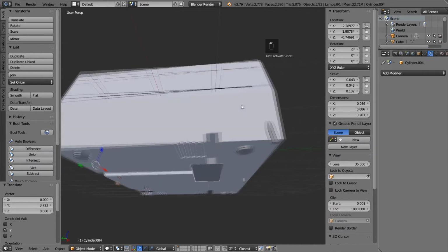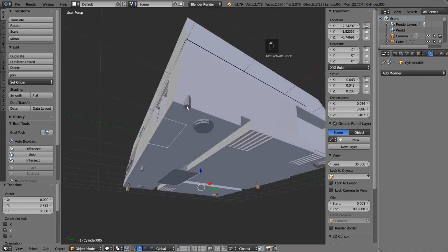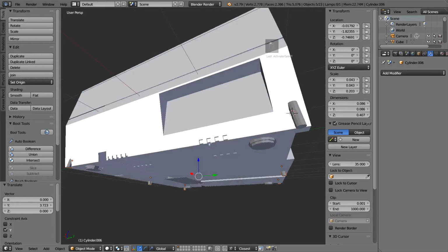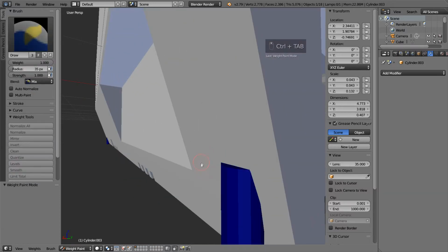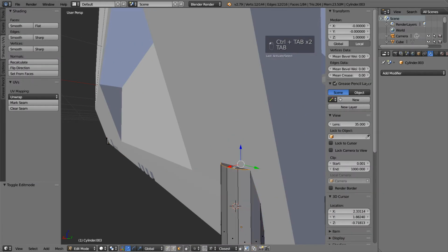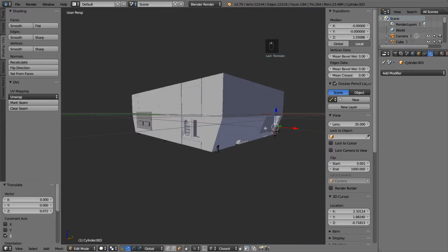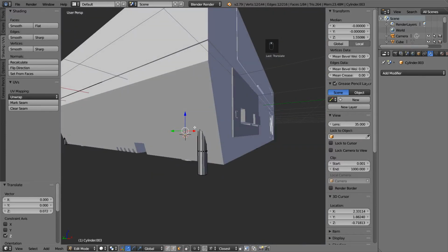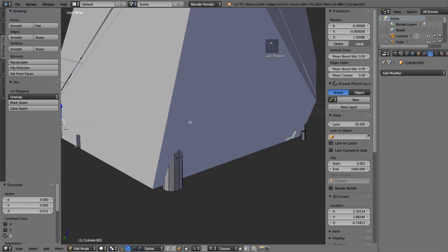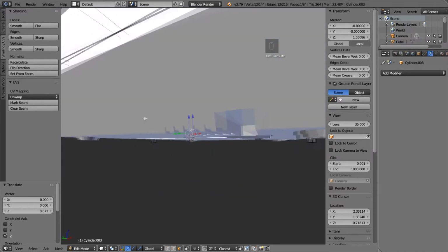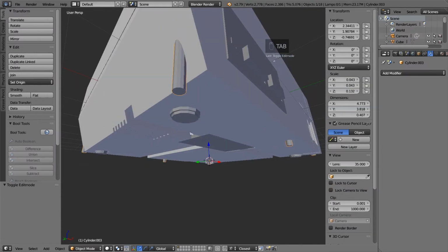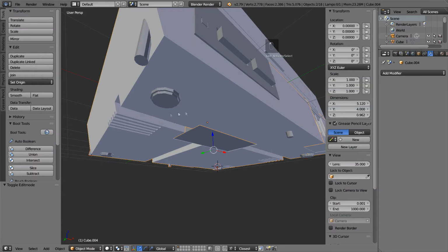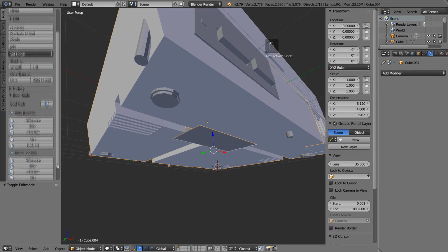Let's select all the cylinders. And then, once selected, we can hit Ctrl J. As you can see, this one is not fully intersecting. So let's bring it up a bit, make sure it's right in there. And all the others are as well. And then let's do a difference Boolean again. It's our favorite tool.